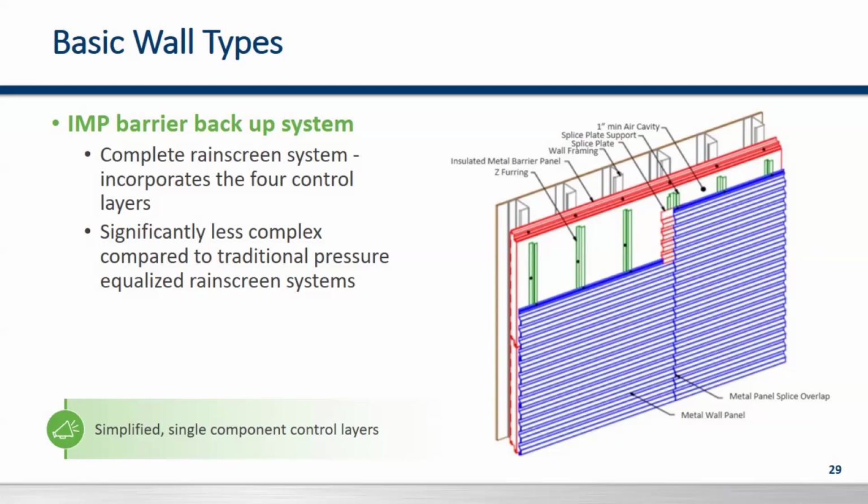So while the insulated metal panels are an absolute barrier, by adding the additional layer of, say, single skin metal in there, we can add that architectural element or mixed use products there, which is providing even more protection over the insulated metal panels, which are already a perfect barrier there. And we do that through the insulated panel, the exterior, say, single skin metal panels, and then some simplified hat channels or Zs. And we'll show you some more examples.